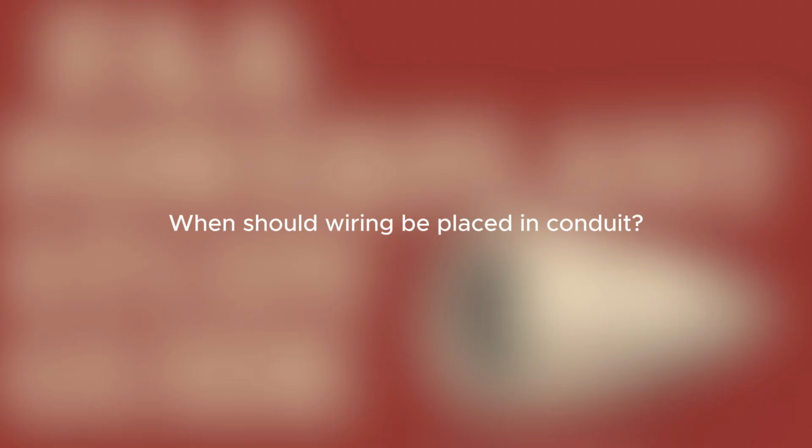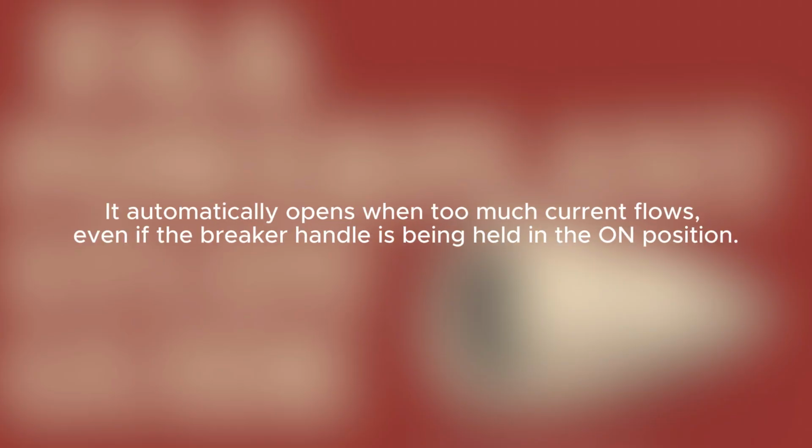When should wiring be placed in conduit? When it passes through areas where it could be damaged, such as a wheel well. What does a trip-free circuit breaker do? It automatically opens when too much current flows, even if the breaker handle is being held in the on position.